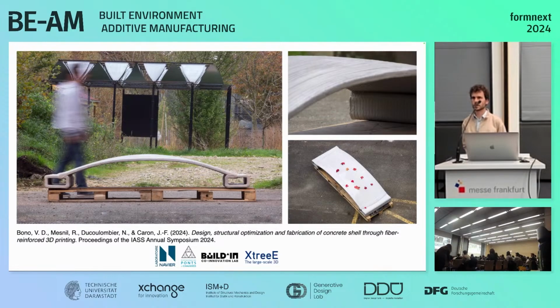But what we just know is that carbon fibers are already well used in reinforcement for concrete. And yes, you could also have glass, but for glass you can have problems due to the alkaline environment, but there are treatments for that for the glass. And we are still quite open on the definition of what material should be used for reinforcement here. Thank you.